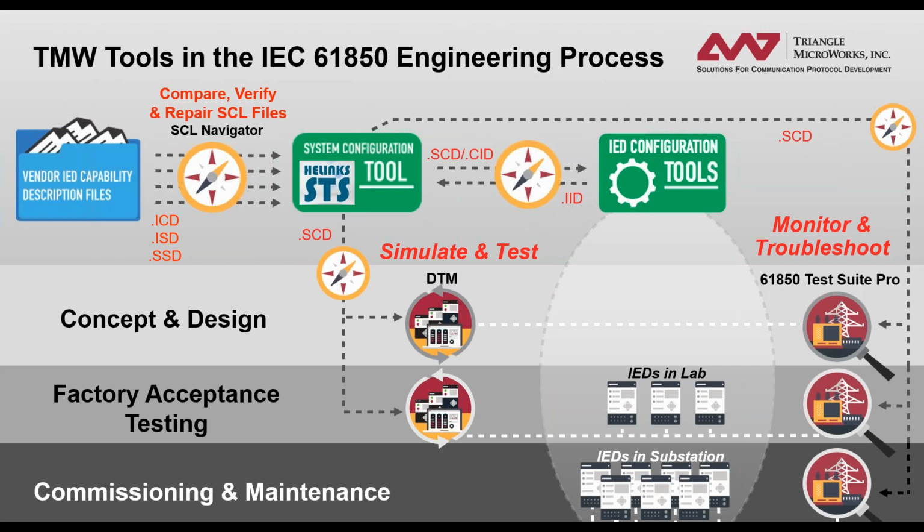And then there is the aspect of the live system where we have the logical node LGOS for the GOOSE supervision that was introduced in the second edition of the standard. There is a status indicating that the IED is currently receiving or subscribing to the message. So with that, you can verify that everything is okay, that the IED really sees the message and is subscribed to it. And there we can also see, when we talk about testing, but that's another topic, if it receives the simulated one or the real one. So that we can see in the logical node LGOS.